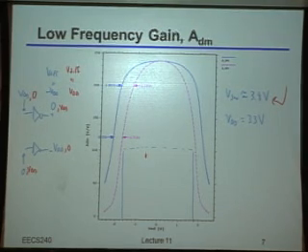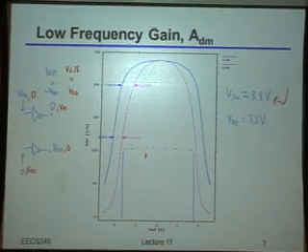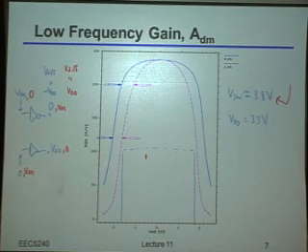And we said that no physics was being broken there because it's a differential circuit. So of course, if one side can swing from VDD to ground, and the other side can also swing from VDD to ground, at the end of the day, you can indeed, at least theoretically, get double the supply voltage in terms of swing. So that's very commonly one of the advantages people quote for differential circuits.